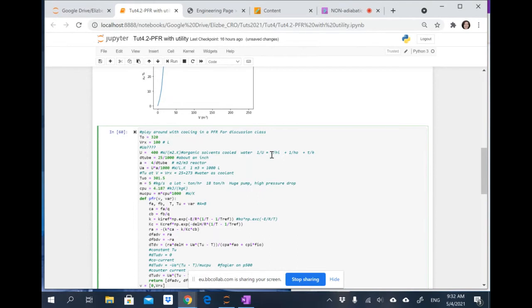But we first just want to get a feel, so I say, okay, let me just confirm now that I've chosen a tube diameter and I know the linear velocity and I've got my mass flow rate of my shell side. Now I can just corroborate that I do in fact get a U value. And so it will be a trial, not only in terms of trialing for that TU value, but the whole design procedure is an iterative procedure. So you will first check, okay, this gives me a more or less design. Now I'm going to fine tune and say, okay, so calculate a more accurate value for U with my given tube number. Rerun. Do I still get that? Do I want to change my tube size maybe?